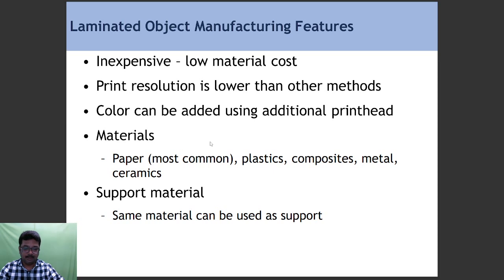Small components require support materials. We can print using LOM, but we won't go for mass production with it. When we require mass production, we move to SLS, DMLS as well as FDM. Those are used for mass production, because no specialized machine is available for mass production with LOM.